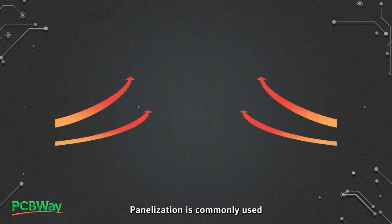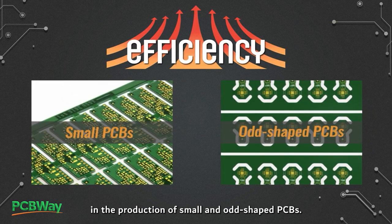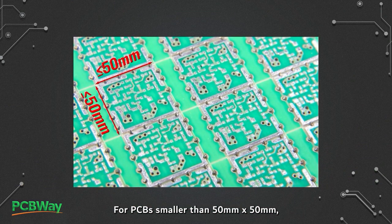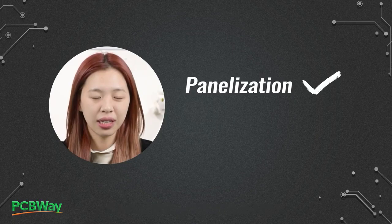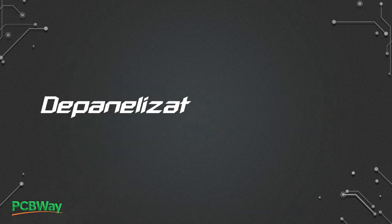Panelization is commonly used to optimize and increase efficiency in the production of small and odd-shaped PCBs. For PCBs smaller than 50 mm by 50 mm, panelization is recommended. So, after the panel production is completed, what are the common ways to depanelize the boards?